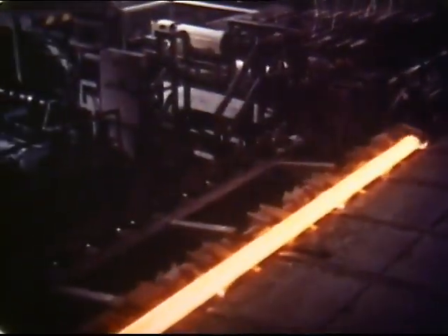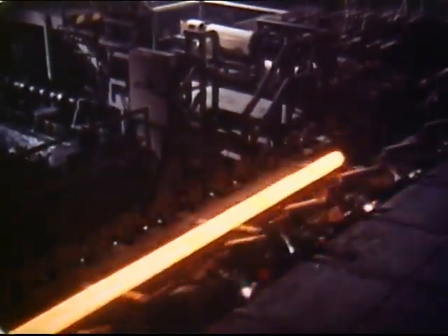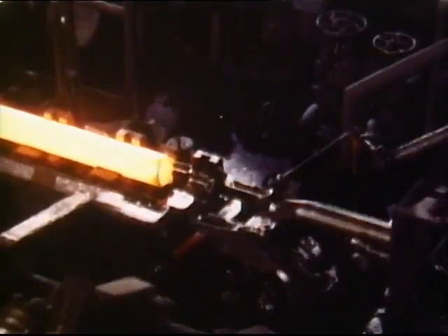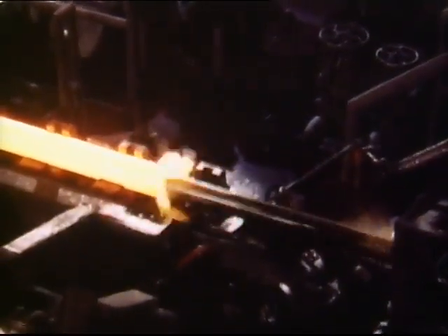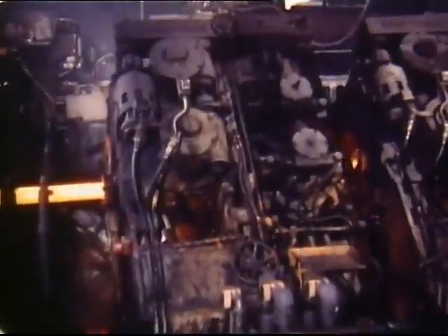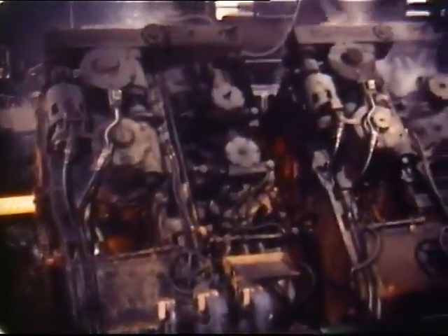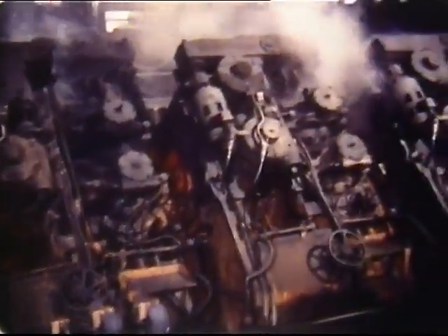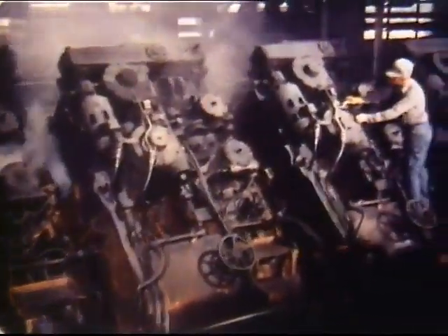From this point on, all operations are entirely automatic. First, a long cylindrical bar or mandrel is inserted into the shell. The bar or mandrel is not fixed as in the piercing mill. It moves forward with the shell around it into the continuous mill. This operation is called rolling on a bar. This part of the continuous mill is called the mandrel mill.